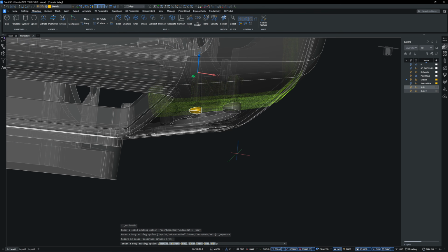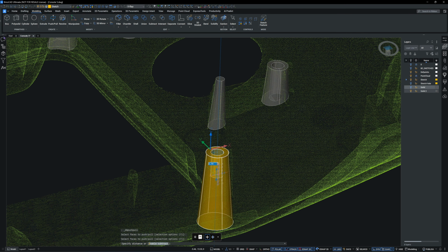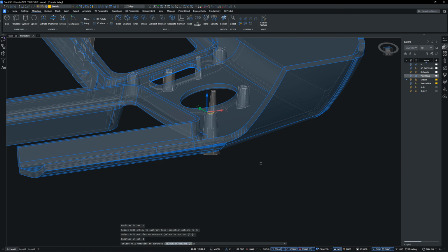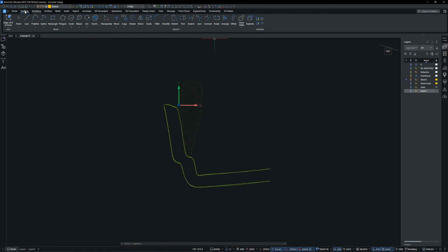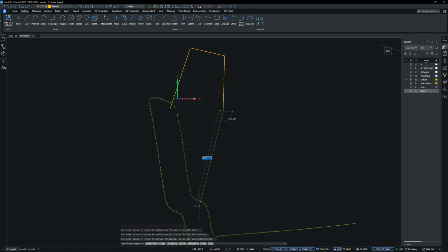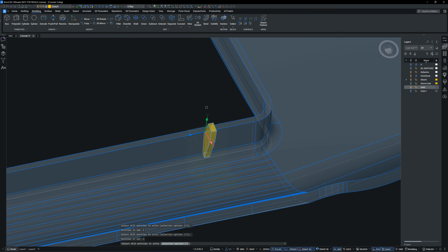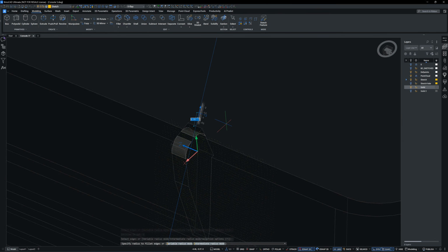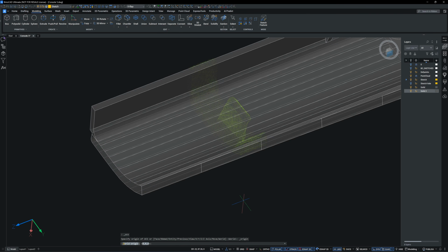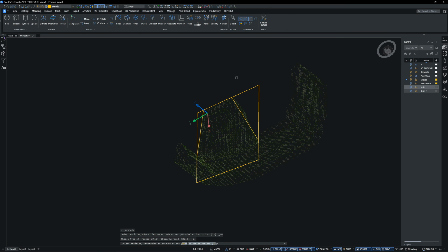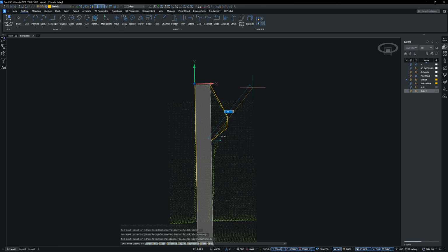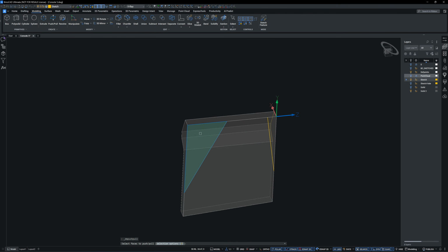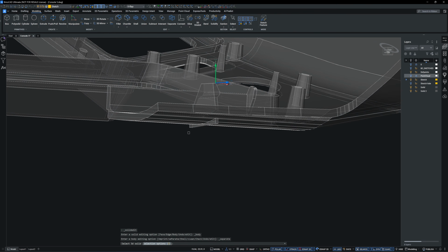This half of the console bezel has 19 clips. Luckily it's symmetrical, so I only need to model one half. For reverse engineering a symmetrical part, you need a high precision laser scanner. The low-cost laser scanner lacks the accuracy for this task. When you mirror your CAD model, the mirror side will never align with the point cloud on the opposite half.